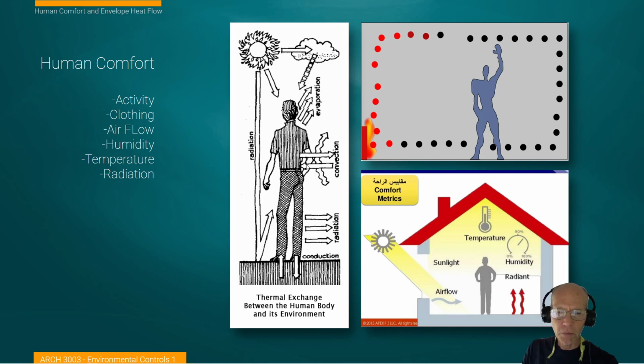There's a little thin film of warm air that surrounds our body. And when there's wind blowing, we get an effect called wind chill, where that warm barrier layer is removed. And we can mitigate that with the addition of clothing and so forth. So I've added a couple of other graphics. This is just to reinforce that idea of radiant heat being warmed in a cool room by a fire that's far distant, because the method of heat transfer is radiation, just like light moving across the room. You only feel it when it strikes a surface and warms it.